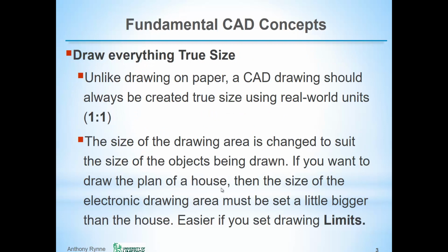So some fundamental AutoCAD or CAD concepts. And the first thing is to realize that in AutoCAD, we draw everything full size 1:1. Now that is irrespective of how big it is or how small it is. So please remember that you don't scale when you draw things. The AutoCAD database remembers the size of all your objects, so by drawing them full size, everything will have the correct dimensions when we add those later.